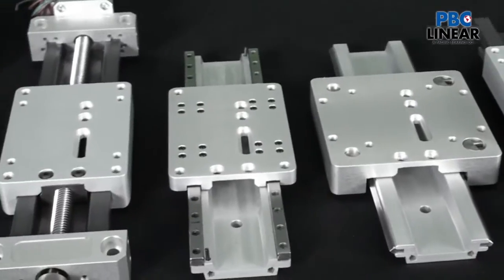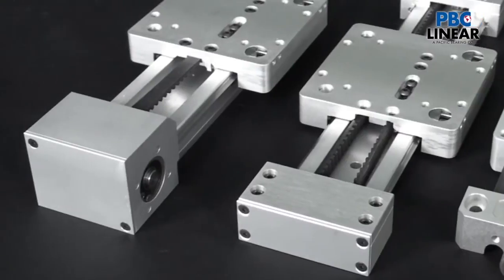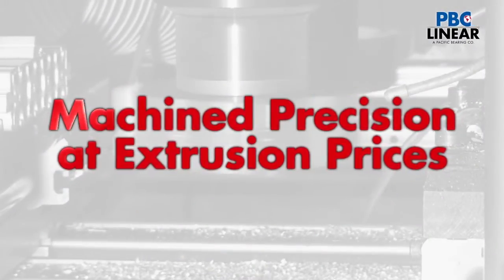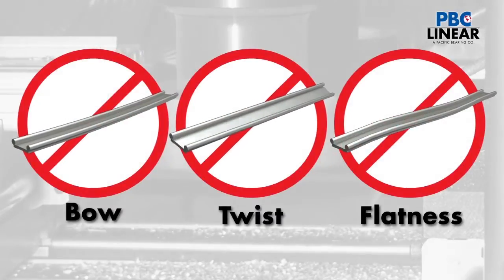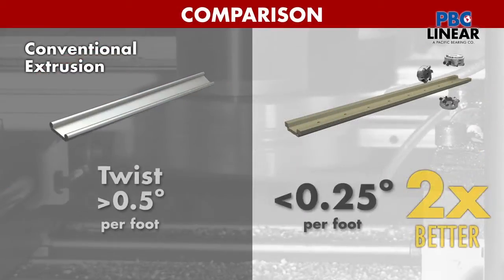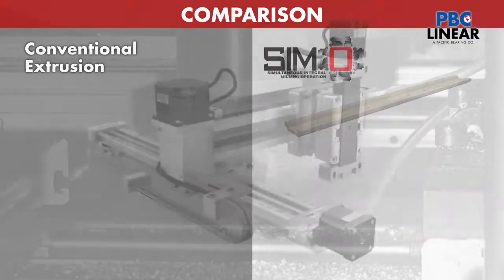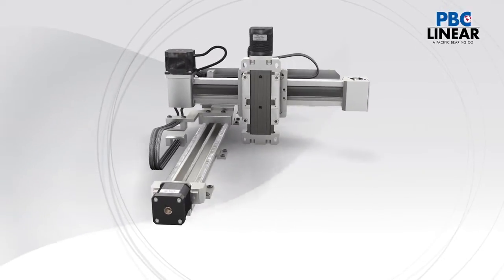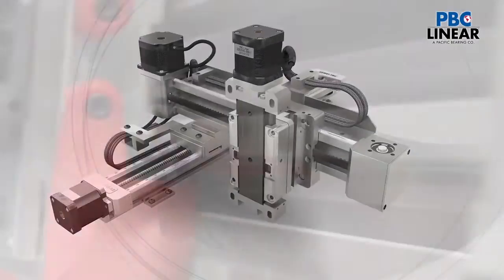Many of the slides and guide rails from PBC Linear offer an alternative to these extremes. Using the simultaneous integral milling operation, or SIMO process, precision linear rails can be produced at extrusion level prices. The accurate tolerances held for straightness and flatness eliminate the bow, twist, and warp, and are ideal for most linear motion applications, fitting well with the capabilities of a variety of drive options as discussed later in this video.